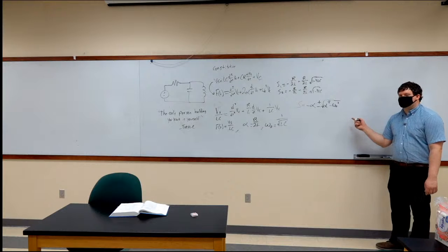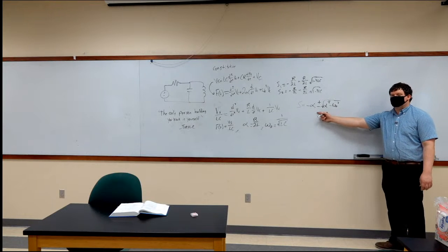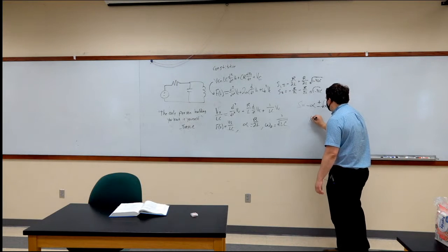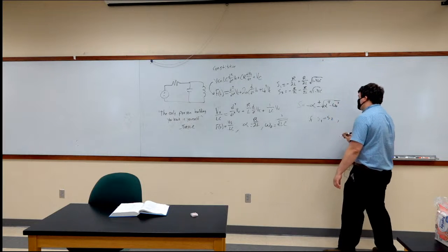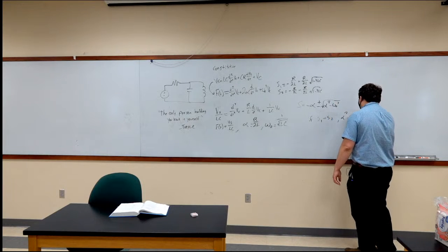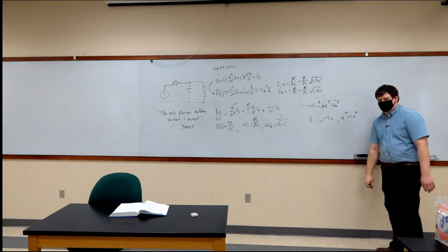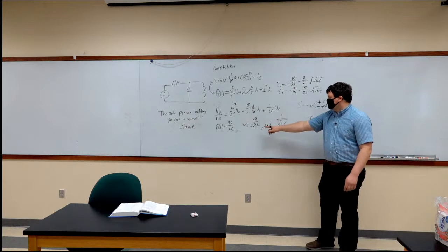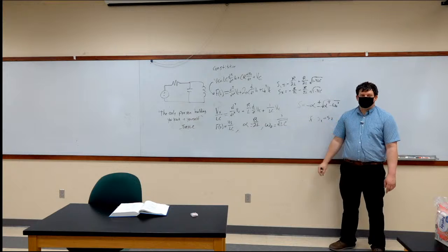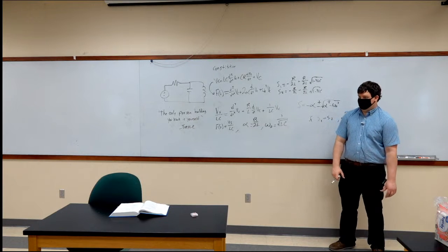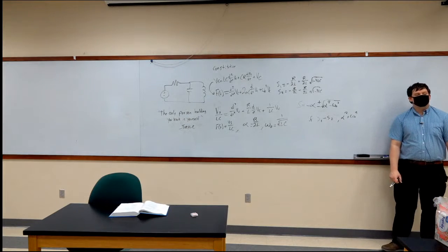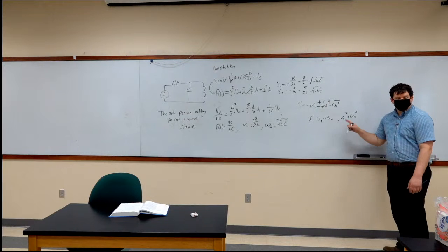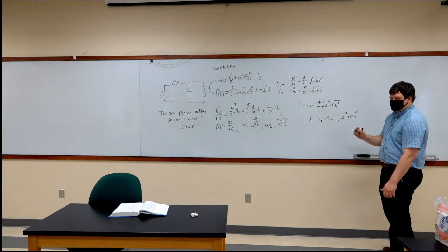Now in the last problem I asked you, what happens when you want your S values to be equal? If S1 equals S2, then that means alpha squared is equal to omega naught squared, which means alpha is equal to omega. If these two terms are equal to each other, this system experiences what's called a singularity, where the behavior is a little unique. If S1 equals S2, there is a very specific solution that we have to estimate.